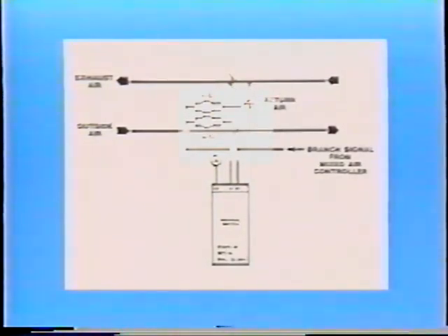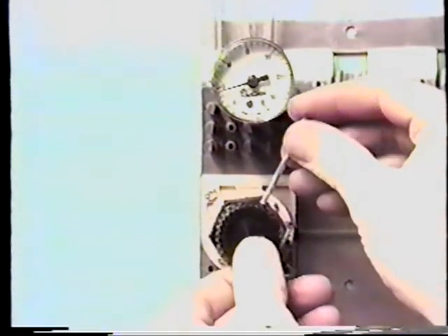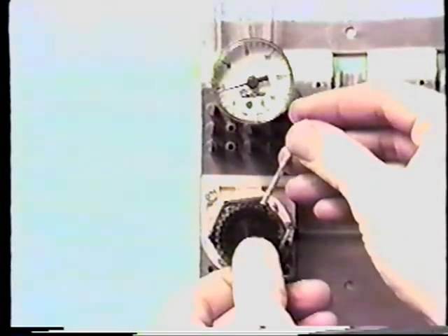In this example, the actuators have a spring range of 4 to 8 psig. It is necessary to adjust the minimum position switch to start at 4 psig. With no pressure on the S1 port, turn the dial until an output pressure of 4 pounds is achieved on the B port. Loosen the 3/32 hex screw on the knob. Rotate the knob counterclockwise until the knob rests on its stop, and tighten the hex screw.